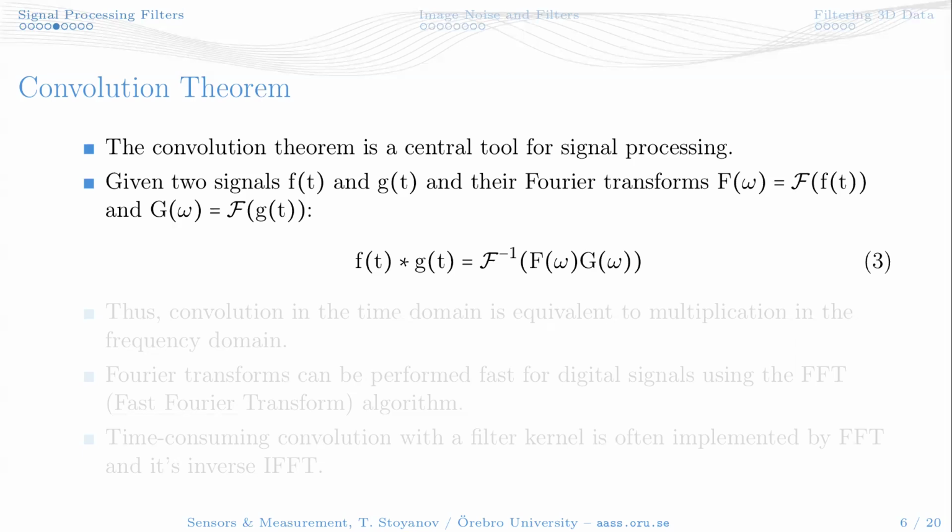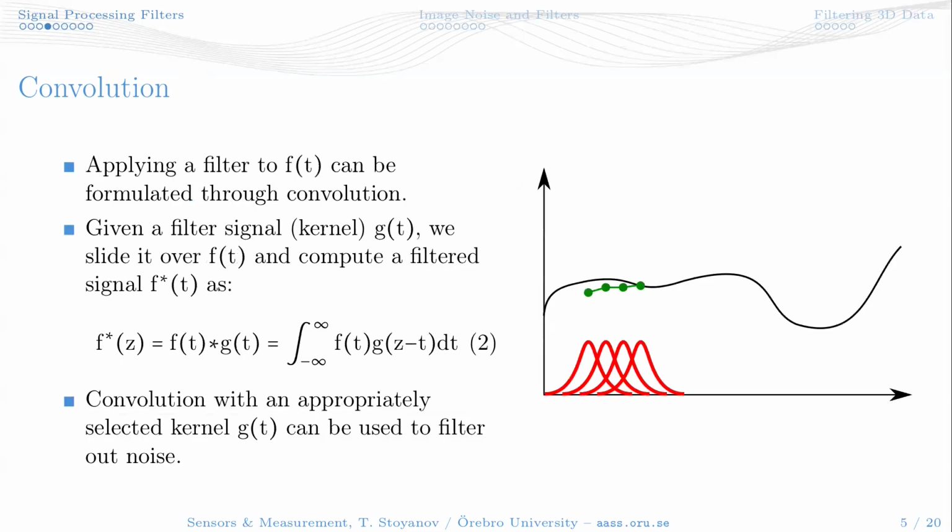So why does this matter? It matters because if you wanted to calculate this integral here, in reality, for two given signals, analytically, this would be very difficult for random signals, right? This filtering kernel here could be anything. If it is a Gaussian, maybe it is possible to do this analytically, but it could be very different kinds of kernels.